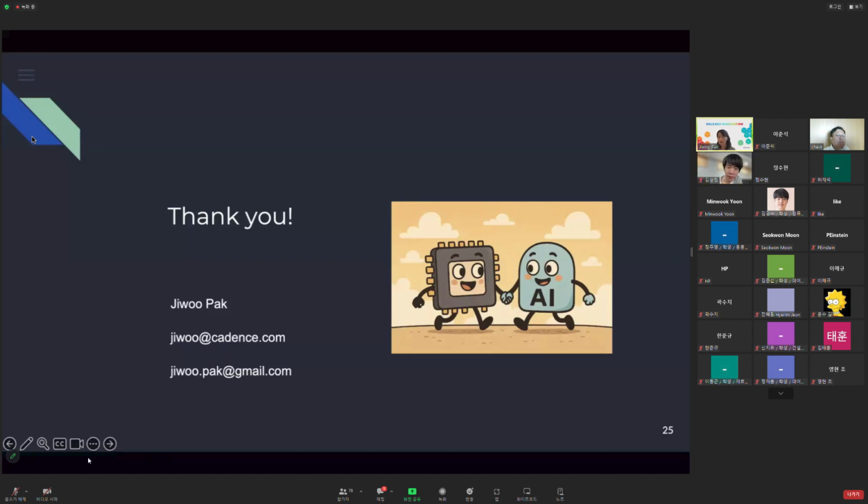That's a really hard question to answer because it really depends on the usage. For example, I mentioned place and route, but there are also optimization teams doing all kinds of timing optimization. Within routing there will be global route and detail route, maybe some DRC cleaning up. And for placement, there will be macro placement, global placement, and detail placement. Depending on the usage, each team can develop their own model, because they have their own problem to solve.